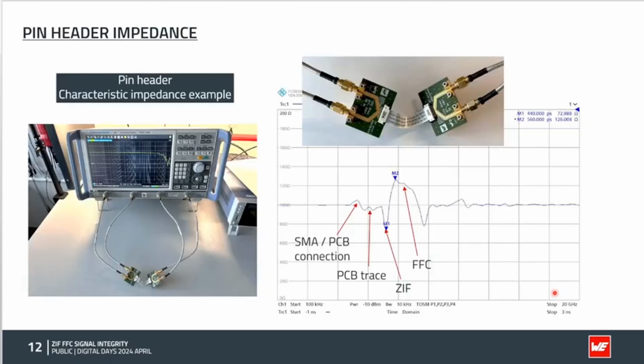So, last thing before we go into the figures, then how the measurements are done. We use a VNA Rohde & Schwarz here, 4 ports, and you send differential signals here, and you do the measurement here. And what you see here is that for the impedance, you send a signal. This is 100 ohm because this is here the measurement of the coax cable, 50 plus 50, this is 100 ohm. Here you've got the connection of the solderless SMA.